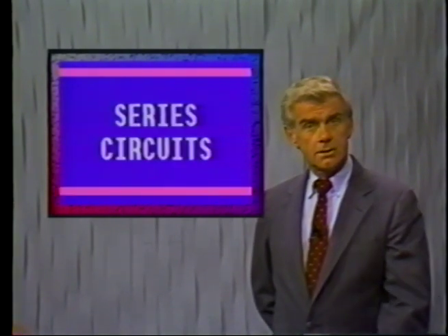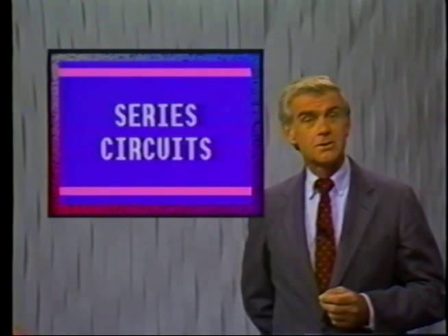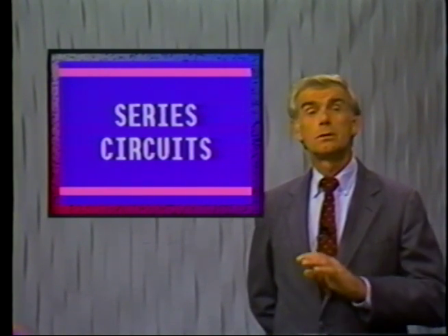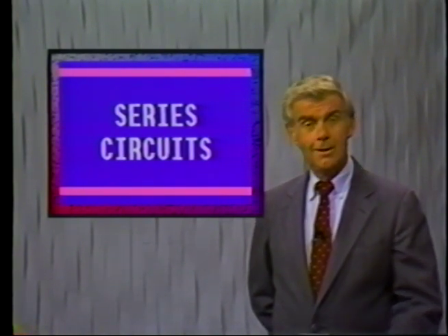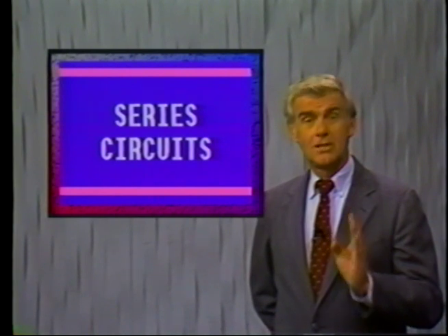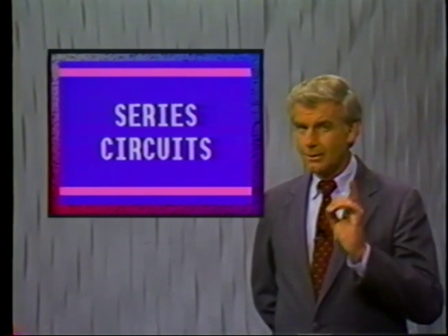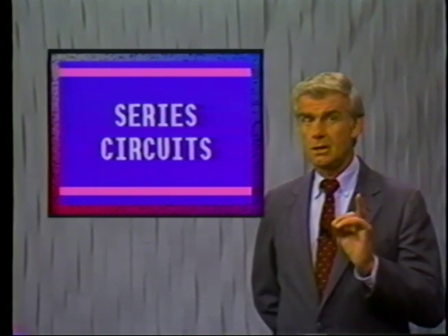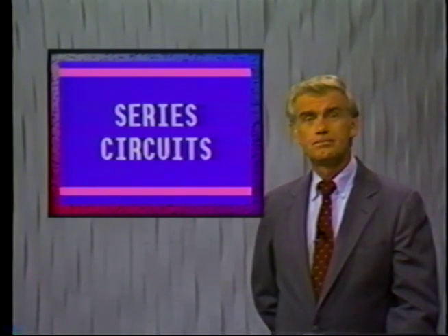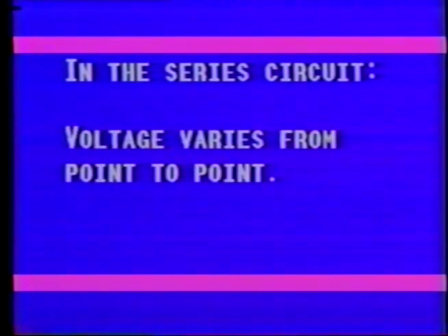This comparative statement deals with the relationship you need to understand about series circuits. Those of us familiar with the differences between parallel and series circuits would already be on to the next question. For the rest of us, however, let's review the difference in these electrical circuits. And don't forget, there's a task sheet covering this information. In the series circuit, we know that current remains the same throughout the circuit. Voltage varies from point to point due to the voltage drop across each point of resistance.